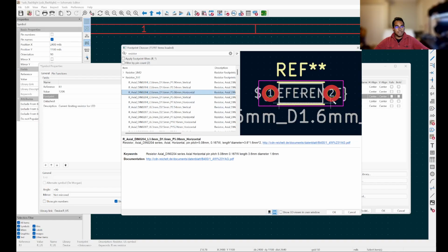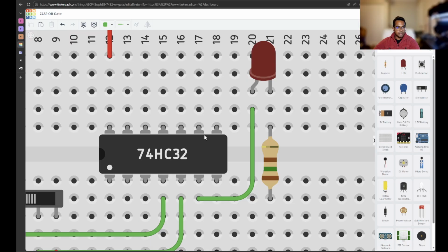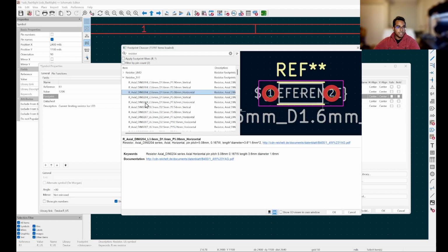And this is a physical representation of what the resistors we saw in Tinkercad would solder through. But typically we want to stick with surface mount resistors for resistances this low, just because they're much easier to obtain, and they're more common, and they're way cheaper than through-hole resistors.